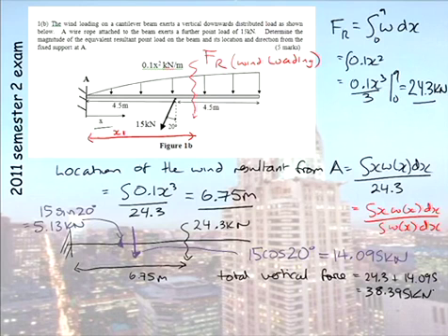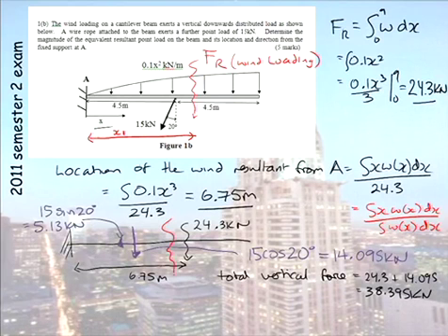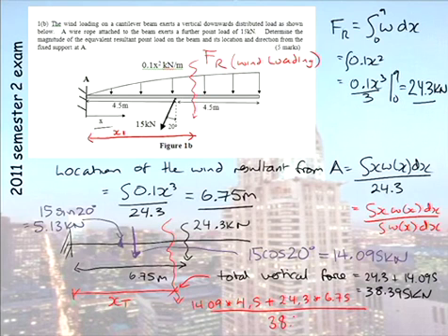Now we work out a new location for our total resultant force. So now we can say, okay, our total vertical force is this one here, and now we need to know where that one's acting. So where does that one act? Well, again, you would say force times distance, your force of 14.09 times the distance of 4.5 where it was acting from A, plus your wind load times the distance that it was acting, 6.75 metres from A, and then you divide by your total load, and that would give you a distance of 5.9.